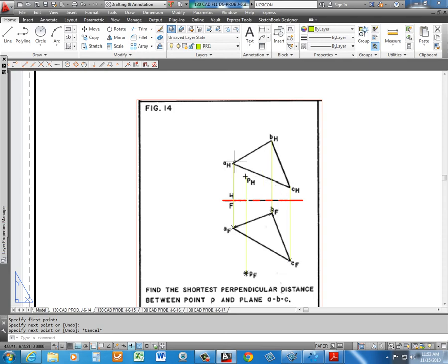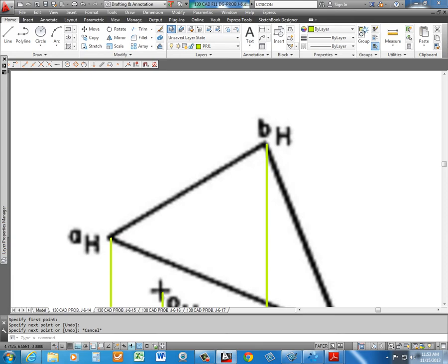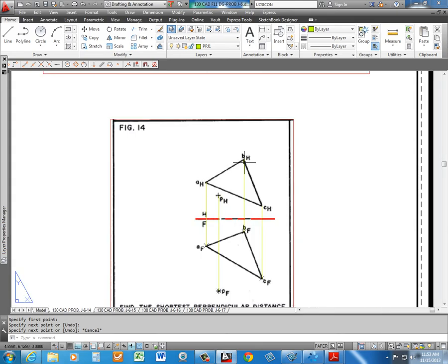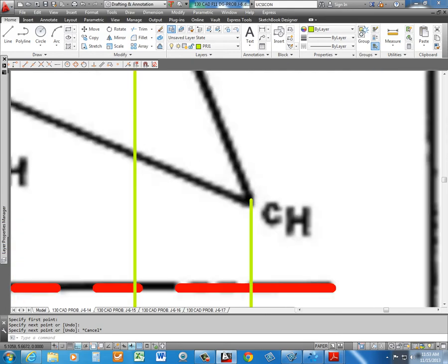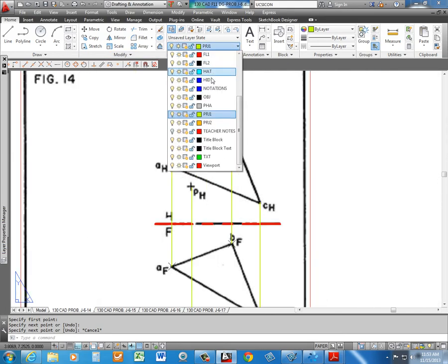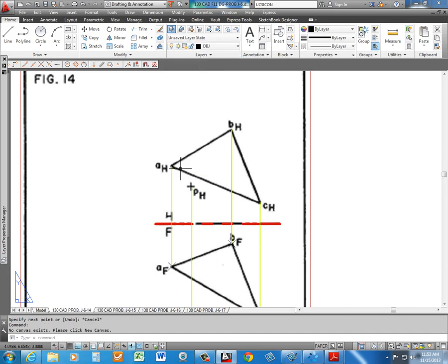Now let's draw our object lines connecting these points. Let's zoom up and see where we're at. Yeah, it's close to it. Pretty close. All right. We do need an endpoint. There we go. Turn off my ortho.